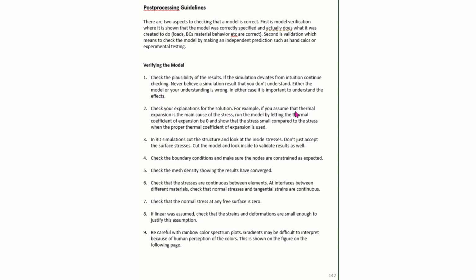For example, if you assume that thermal expansion is the main cause of the stress, run the model by letting the thermal coefficient of expansion be 0 and show that the stress is small compared to the stress when the proper thermal coefficient of expansion is used.